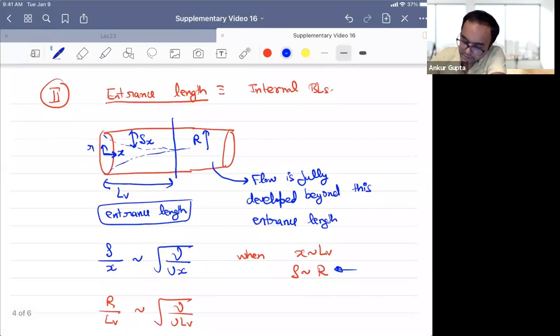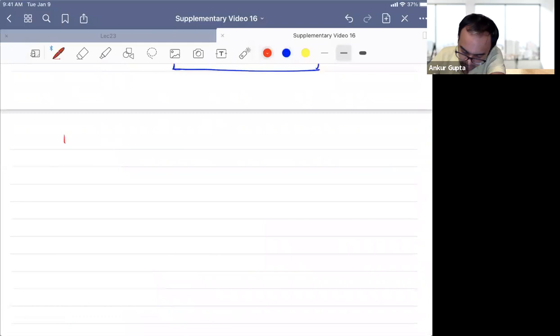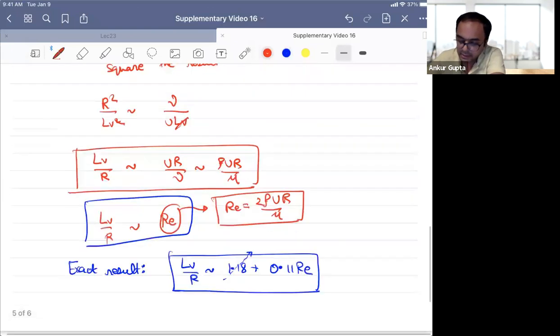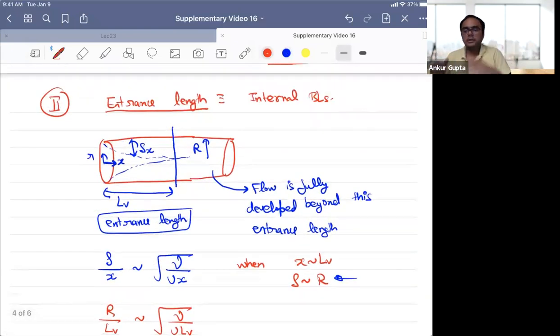The third thing we want to discuss is the flow around objects, the drag around objects. Always classify any flow type into these two parts. One is flow predominantly in one direction, like channel flow or flow between two plates. The other is flow around an object, which is typically bidirectional. I want to emphasize the difference here. In this case, the drag force will be most predominantly the shear stress, because the skin drag is basically in the x direction, and the pressure is normal, so it's in the radial direction.